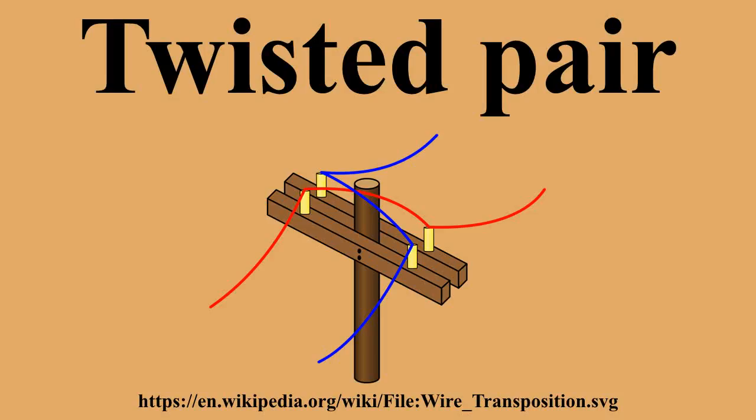This method starts to fail when the noise source is close to the signal wires. The closer wire will couple with the noise more strongly, and the common mode rejection of the receiver will fail to eliminate it. This problem is especially apparent in telecommunication cables, where pairs in the same cable lie next to each other for many miles. One pair can induce crosstalk in another, and it is additive along the length of the cable.